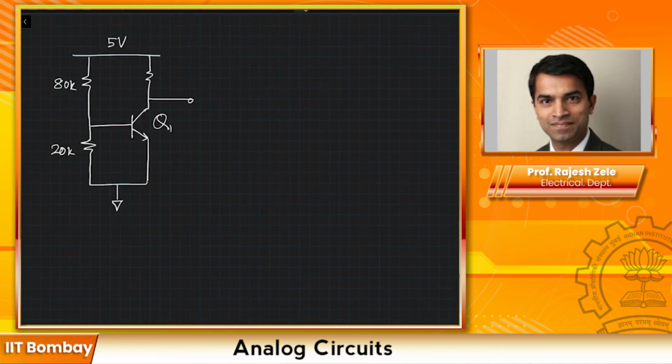Now we will repeat the same example as before, except for one change. In this particular change, I am going to increase the resistor R3. Originally we had it to be 1.333K. I'm just going to move the decimal point to the second spot, so it's 13.33K. That's the only change I have done. And let's analyze what happens in this circuit. Nothing has changed at the input, so the input will still look the same.